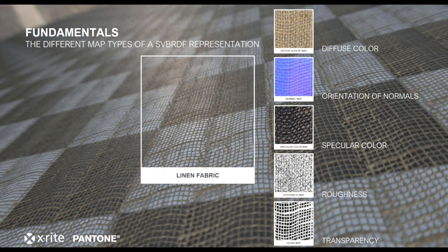And then the transparency, this is seeing all the way through an object and having soft edges and things like that. This is particularly useful for meshes. We are currently working on subsurface scattering, so that's plastics, homogeneous plastics. We also have height maps and clear coat maps and a few others. These are not shown specifically in this sample, because not every material has all those different characteristics to it. So all of these come together to produce a material format, and they're all included in the single AxF file.